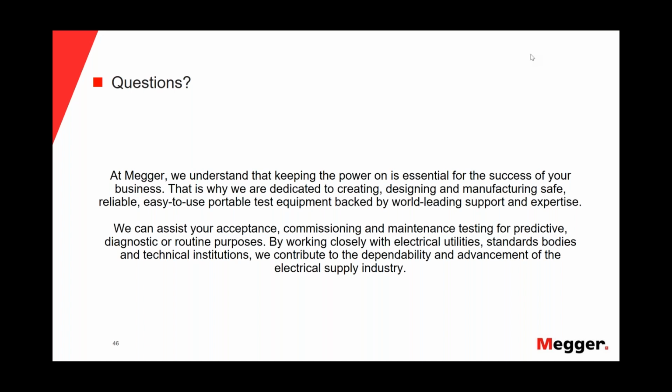So now you can imagine, if you store something out in the Texas heat over that number of years, there is a lot of aging going on in the polymeric material. When we talk about aging, it's not only electrical aging, it's also temperature aging, it's UV aging, because they have a lot of UV exposure, and so on. So it's hard to say, because it all depends how this cable was stored over this period of time.